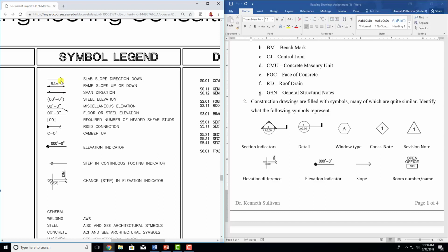The most common slopes are going to be on your roof or in a parking lot where you need to slope it towards a drain. This is a car dealership, so there are going to be floor drains in various places in case of oil spills or in case they need to wash something. And it's going to show sloping. It will also be in every bathroom because there's always a floor drain in the bathroom. If there's a shower, or if you're doing a research lab that has one of those emergency showers, you're going to have to slope it. So just keep in mind that different symbols, even though you might think, oh, it's an arrow pointing towards something, that might not be the case, and it probably isn't the case actually.